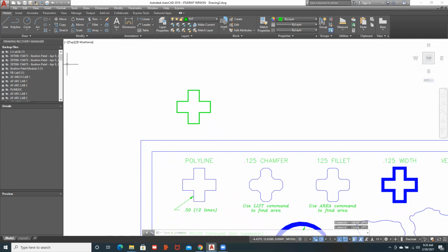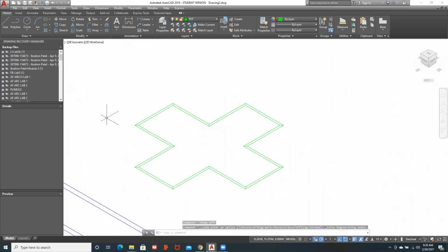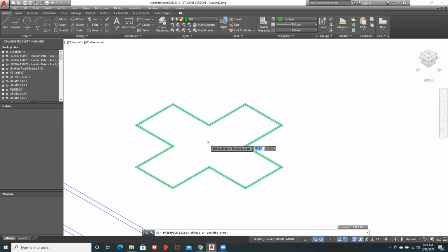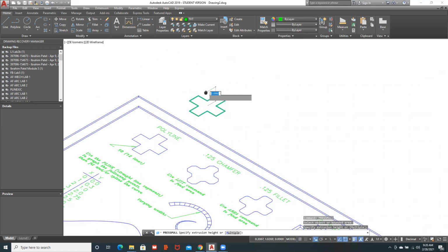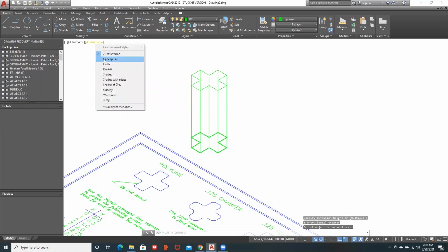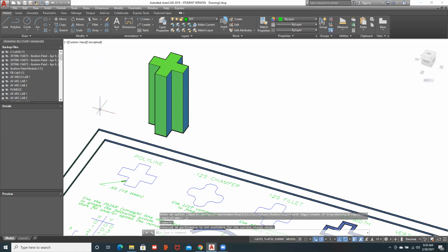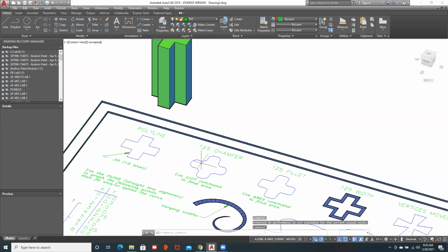And so we'll take these geometries and model them by going into an isometric view. And then we can do things like press pull it. Remember, as you're working with AutoCAD, it does everything better in wireframe. It glitches a little bit in conceptual, but that depends on your graphics card. So here, if I put a conceptual view on this, I can then take that and 3D print it and use it for something. The same with this, if I press pull and just extrude.